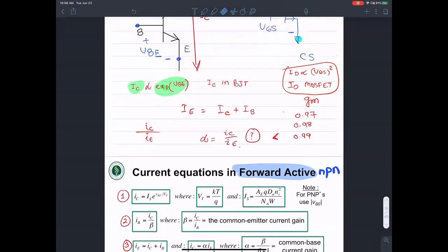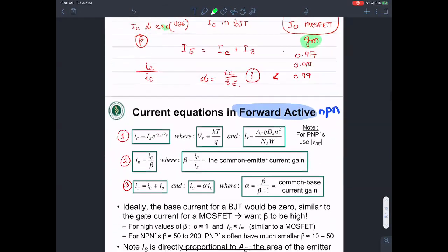And we can talk about that in the example today. But typically what happens is when people moved from BJTs to MOSFETs in terms of technology usage, not all the designers were extremely happy with the lower gain values, lower gm, transconductance. The underlying intrinsic gain values are lower for MOSFETs compared to BJTs.